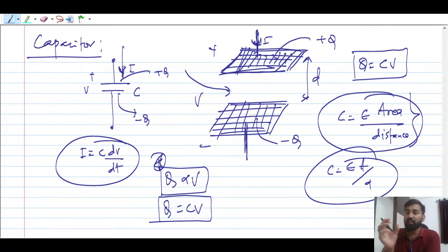These are the units. And they also specify one voltage over there, like 100 volt, 2 volt, 5 volt, 10 volt. What is that voltage? That voltage is known as the breakdown voltage, guys. It means this much voltage your capacitor can withstand. If you apply more voltage than that, your capacitor will be gone, it will be broken. So breakdown voltage is very important.